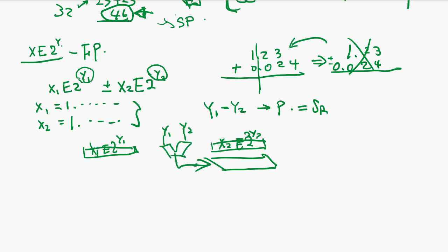Sorry, I'm getting so many interrupts. Let's see. What we have to do is compare the exponent portion first and convert into a positive number, and use this as the amount of shift, and you have to shift right. So it's going to be 0 point so and so, 1 0 1 1 0, this kind of number, and this number is added to or subtracted from the number which is 1 point.